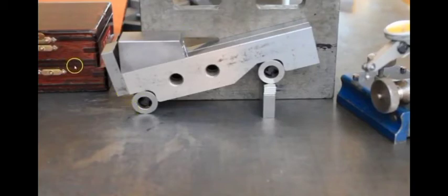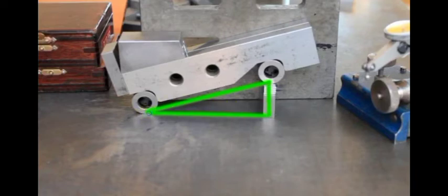It's called a sine bar for good reason, because these points here are exactly 100mm. That's the hypotenuse of a triangle. The slip gauge stack is the opposite side, and we form a triangle there. So we need to apply a bit of secondary school or high school trig to find the exact height of slips required to create the 15 degree angle that we require.